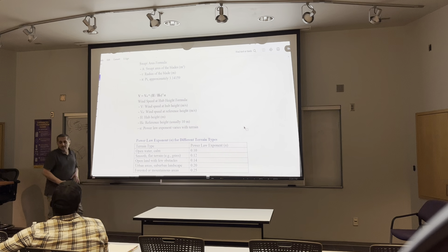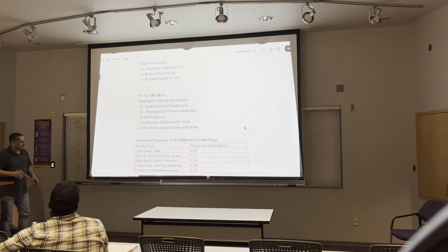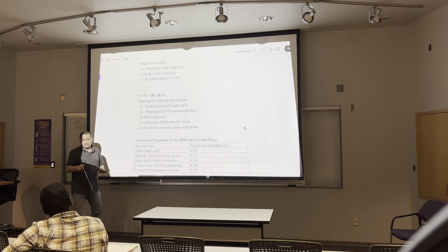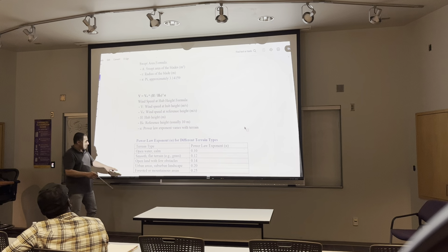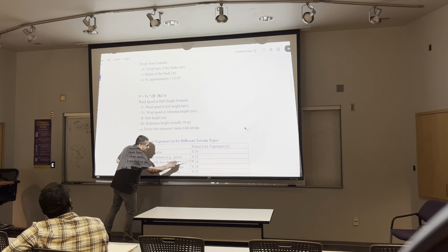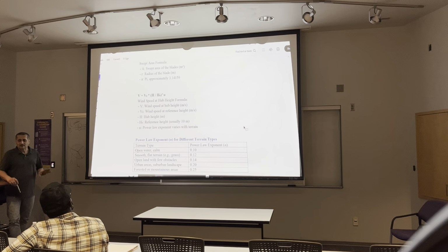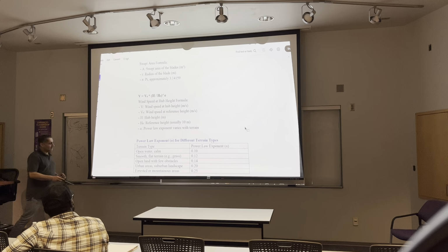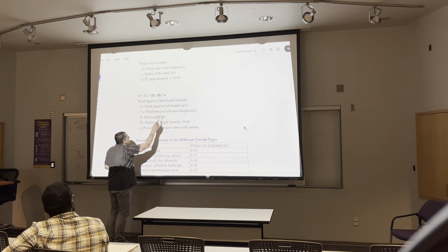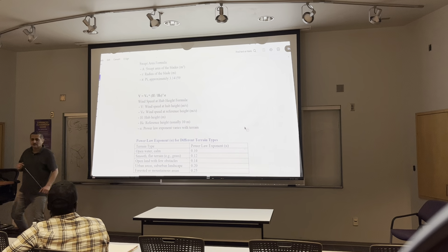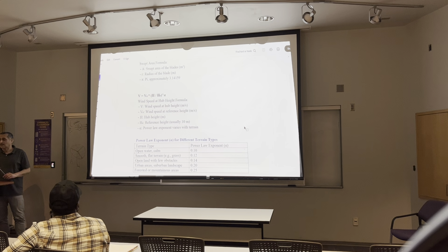As standard, if the example, question or assignment does not mention it, select open land. Open land, select alpha 0.14. Alpha here is 0.14, standard, because the common use is alpha 0.14.